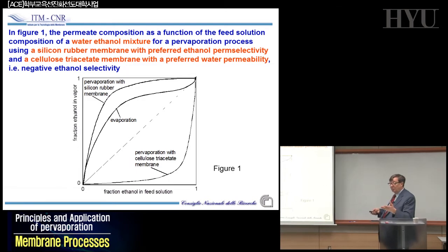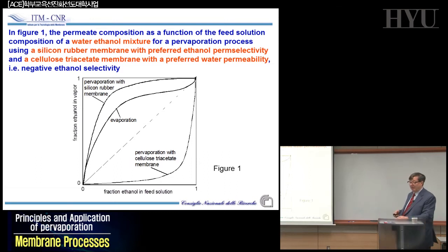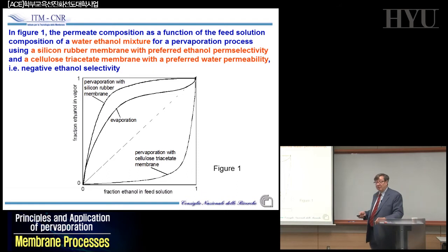If you want to use alcohol as an alternative to diesel or to the traditional oil products, as you know, they are already doing in Brazil, and more biofuels are suggested, you have a problem that alcohol and water are forming an azeotrope. And they form an azeotrope around 93% of alcohol and water. So there's not too much water.